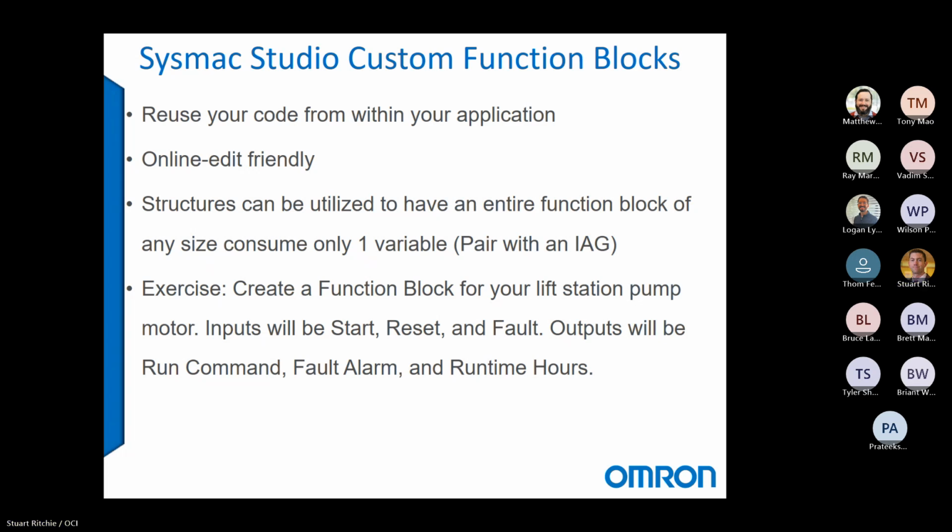Now, they are online edit friendly, which is a very nice feature. So when we edit our function blocks, we edit the base instance of our function block, and that change is duplicated on every instance of the function block on the next scan cycle. So we will be doing an example of an online edit on our function blocks once we have them in our project.